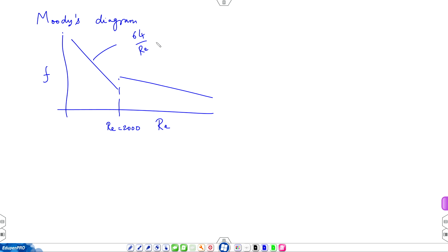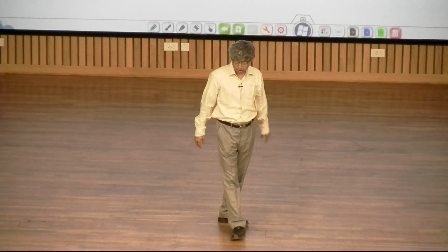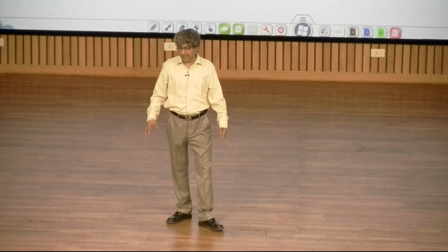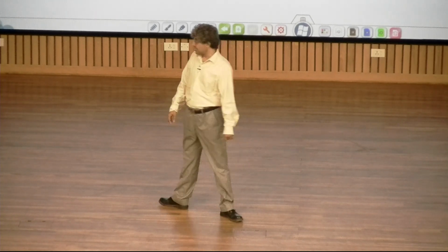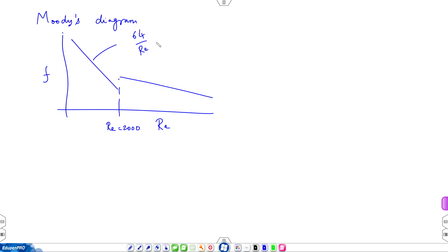It is a very powerful validation of the Navier-Stokes formulation. But the next question is, why does it fail for RE greater than 2000? Experiments show that, what experiments? I have shown you the videos, that flow becomes intrinsically unsteady. So, you can no longer drop the time derivative. If you include time derivative, then there is a hope of getting into the second branch. But the first branch holds for steady flow up to RE equal to 2000.